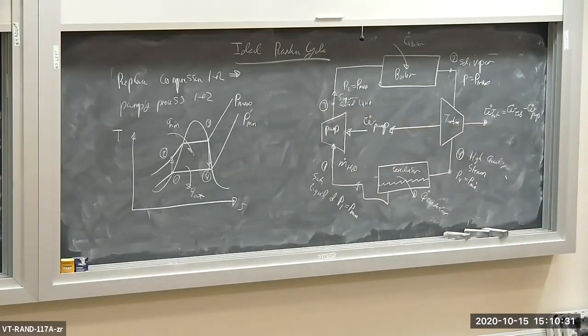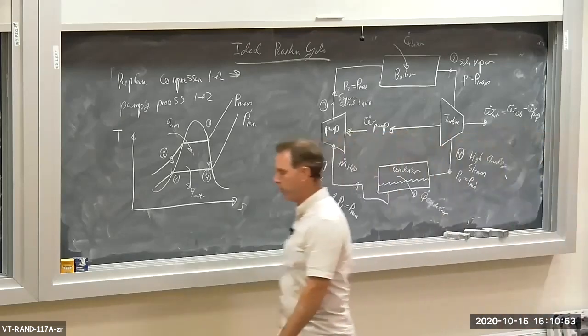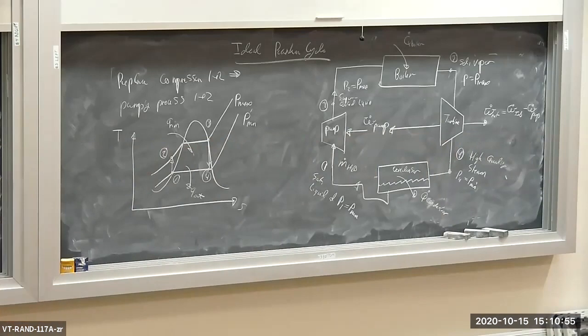So it uses H2O as a working fluid. We have phase changes going on. We're operating at times within the dome. Definitely not using air. Definitely can't use ideal gas law. So we're stuck with saturation tables, superheated vapor tables. Maybe you'll have a problem where we have superheat. Okay? Who knows? So we're dealing with H2O.